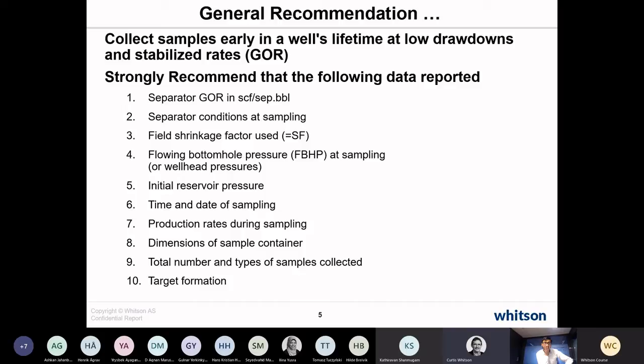Now, usually we don't have equation of state models that include, like in reservoir simulation, the water, H2O, as a component. You can do that on the processing side. That's fairly common. You have some modules in PVTSim and HYSYS, models like that which are doing surface processing. They actually have H2O and even the solids in the H2O as components. And the partitioning of the gas, the oil, and the water phases, the partitioning of components amongst the three phases, can be predicted by a cubic equation of state quite accurately.